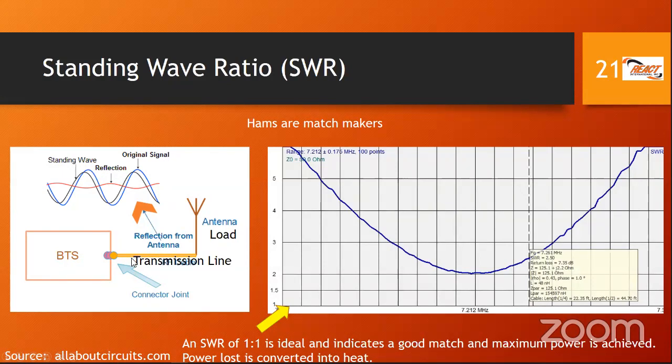You will see for cable TV, RG59 and RG6 and so on, that you use for your cable TV, that will run coaxial cable. If you look at it, you'll see RG6 or RG59. And when you look at it, you'll see 75 ohms. You should not use that for amateur radio. Not that you cannot, right?